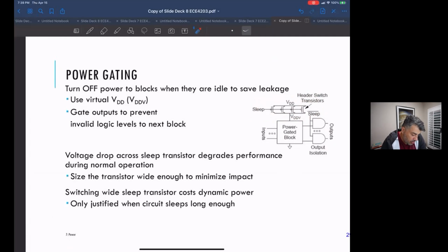And obviously that's sort of like the nuclear option, to make sure that's as low as you can go in power consumption. And the idea is that this only works if you have special transistors that are particularly high threshold, that won't allow leakage themselves when you're trying to turn off a circuit.